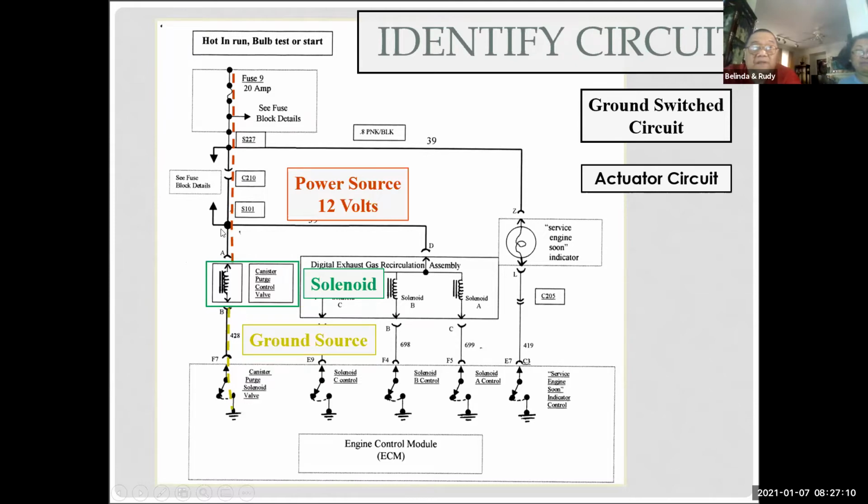You mean to say, Mr. Brian, if you have short to ground, all the current is going and breaking the fuse because there's no load. Right, there's no load. So you blow the fuse, the load wouldn't work. Right, all the current's going to go through the short. Actually, it won't all go through. You know that from parallel circuits. If this was energized, some current would still flow through this and the rest would go because it creates a parallel circuit to ground.